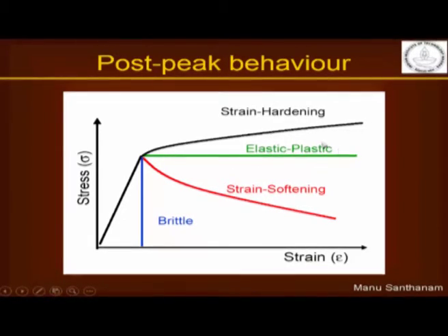In most models for ductile metals like mild steel, we assume an elastic plastic relationship in which after yielding there is steady flow of the material, that means absolutely no increase of stress with increase in deformation. In concrete we have what is called strain softening behavior, in which after we reach the peak stress, the stress actually starts reducing with an increase of the displacement of your concrete.